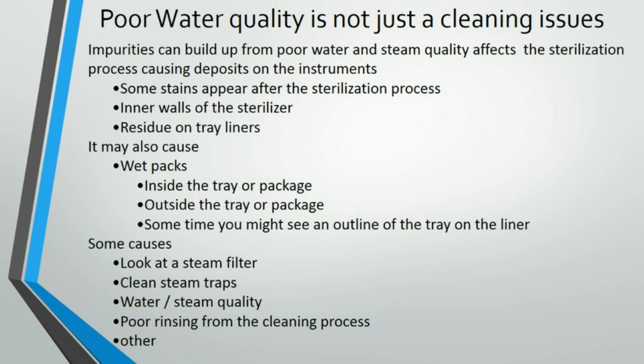So some causes for those: steam filters. There are a few steam filters throughout your steam lines, and that totally could be an issue. The cleaning of your steam traps absolutely can affect it. Your steam or water quality coming into your boiler and then out of it, because those have to be treated as well, can be a problem. And then poor rinsing from the cleaning process. And then there can be other factors that affect it as well.